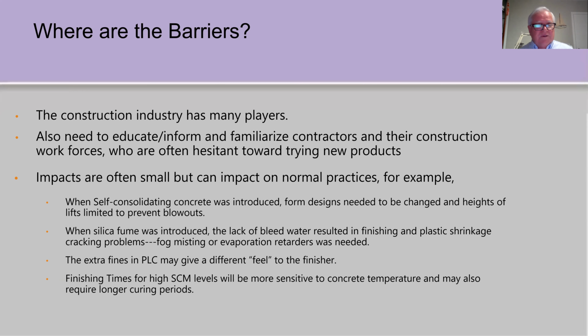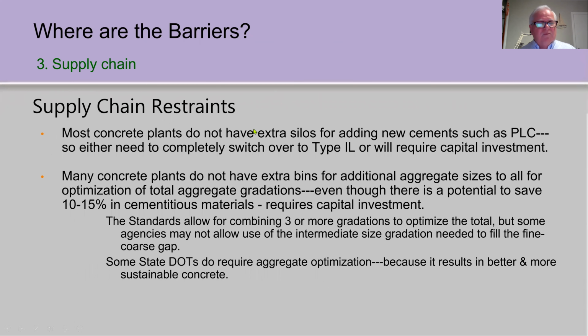Portland limestone cement, for example, may feel different, and the timing for finishing high SCM mixes may be more sensitive to concrete temperature and the amount of SCMs. As long as they know how to do things, they can do it. But when they don't know, it's a problem.